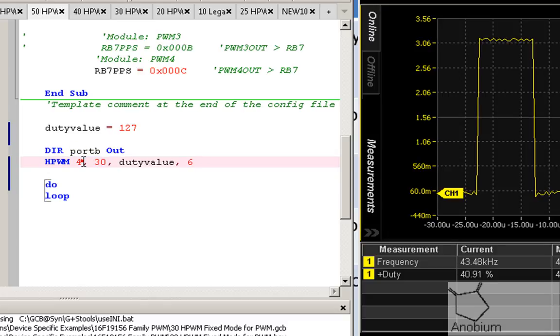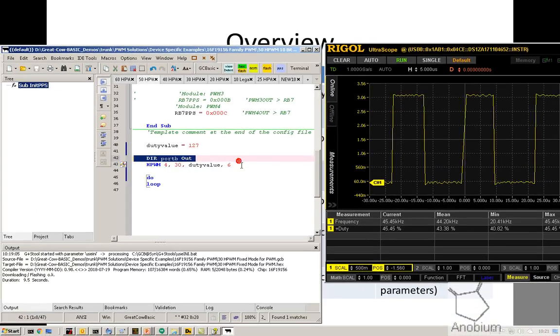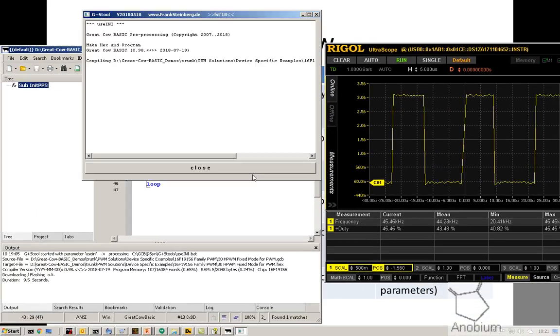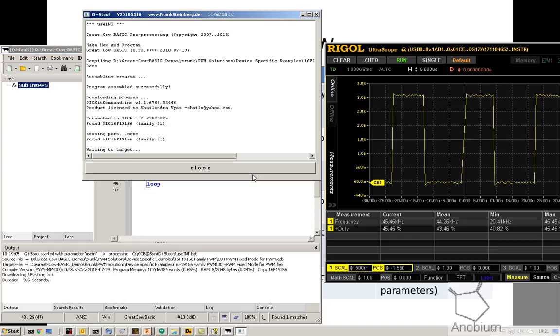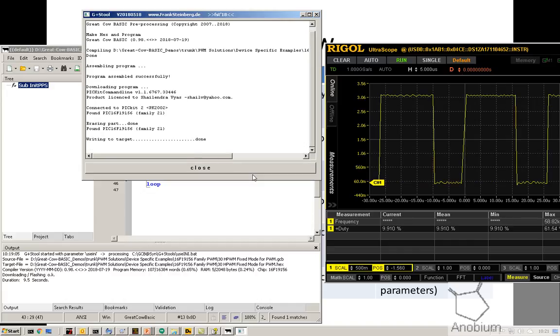I've got a channel number. Oh, now look, I got PWM4, so I put a 4 in here now. I'll show you a cheaty way of understanding this stuff. Some of the newer chips take 4 parameters. You could put 5 in actual fact, and the 5th parameter would be the resolution. You can actually pass it a 10-bit value as well.